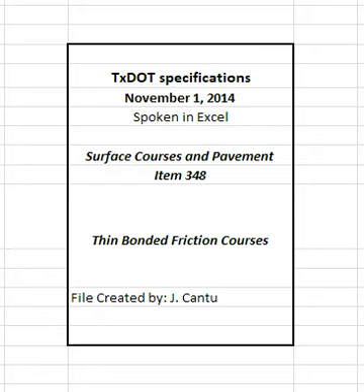The aging ratio is the DSR value of the extracted binder divided by the DSR value of the original unaged binder. Obtain DSR values in accordance with Tex T315 at the specified high temperature performance grade of the asphalt. The engineer may require removal and replacement of the defective material at the contractor's expense. The asphalt binder will be recovered for testing from production samples or cores in accordance with Tex 211-F.